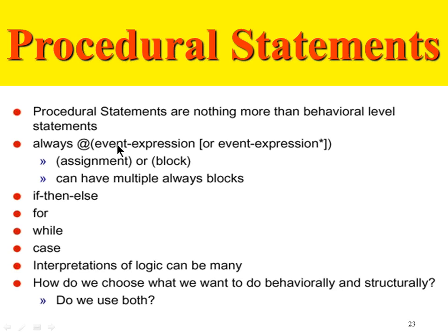It can have one or multiple signals. It can also be dependent on a clock, the edge of the clock, the pos edge of the clock, or the neg edge of the clock. So you can have any of those in the sensitivity list. Anything in the bracket is called the sensitivity list. This always block is sensitive to those signals. Any change in those signal values will trigger the always block, and internally, whatever logic is described inside the always block will be executed.